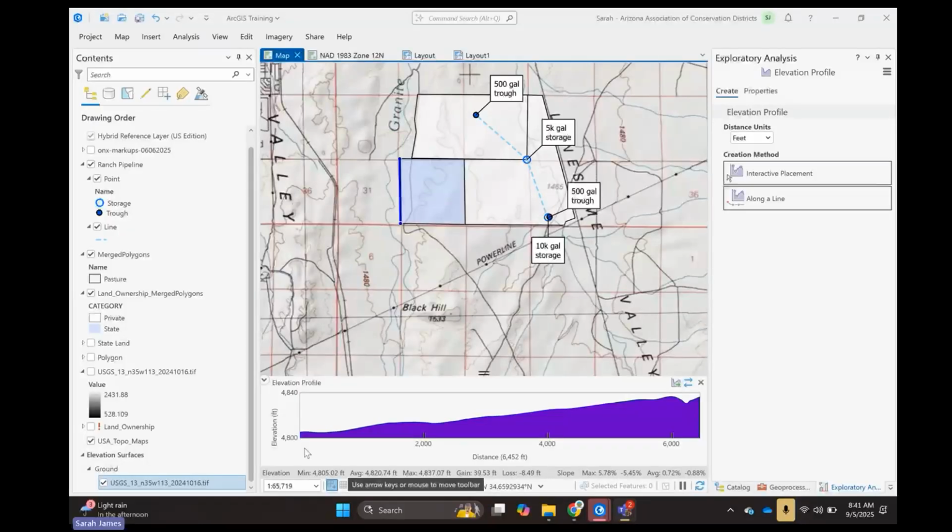It is always good to double check with actual topo lines from a map to make sure it's calculating correctly, just to make sure that somewhere in the metadata it didn't get transferred between meters and feet incorrectly. And I have gone ahead and checked that with this.